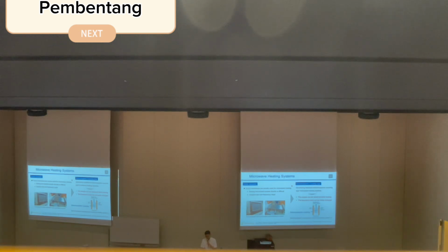On the other hand, a new type of microwave heating system, which is called the electromagnetic coupling type microwave heating system, was developed in my laboratory. This system contains two resonators, which are microstrip resonators on the substrate, and the heated sample is arranged between the resonators, and then the sample is heated by the non-radiative microwave from these two resonators.